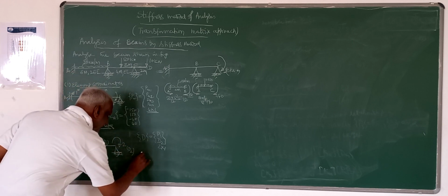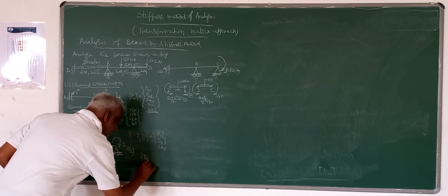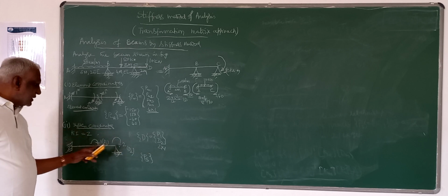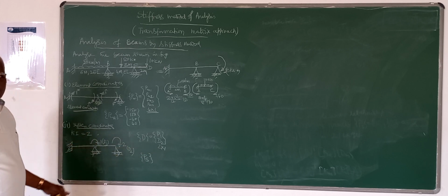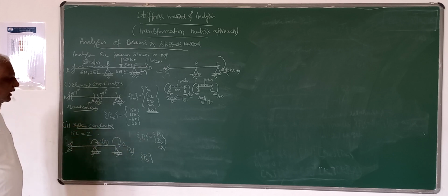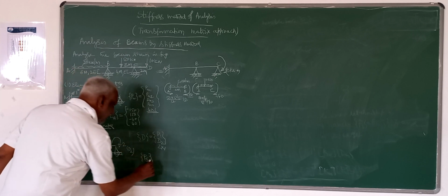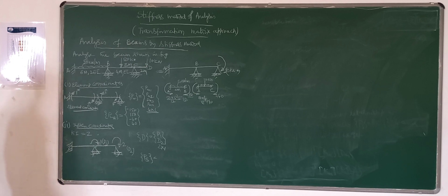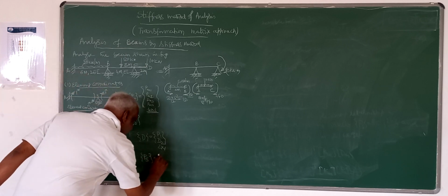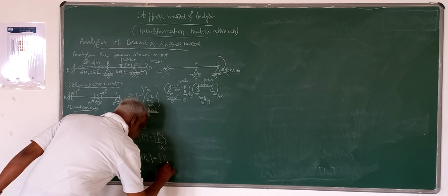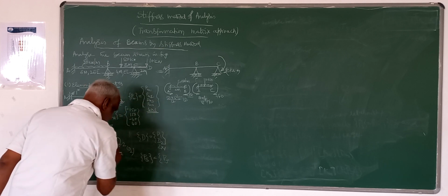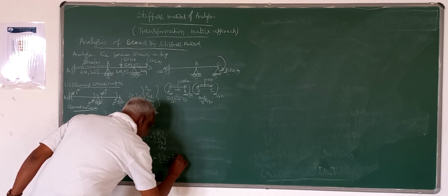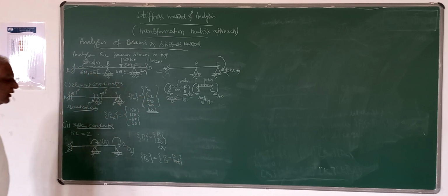And now we can determine this load in the global element, because this is with respect to system coordinates only. We are evaluating the displacements and corresponding to that, whatever load is there, we have to calculate. And this load is nothing but the joint load given corresponding to these coordinates minus PA due to equivalent member fixed action.